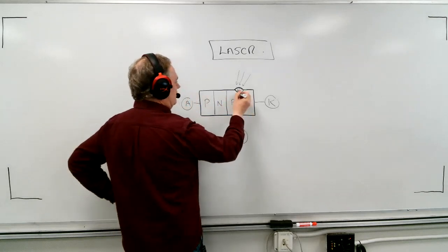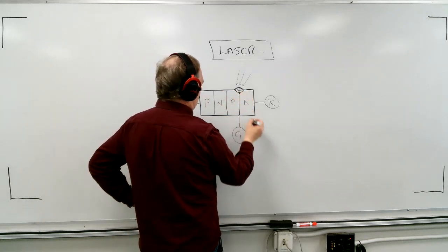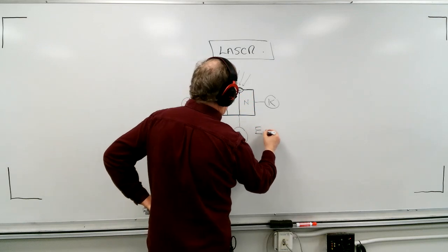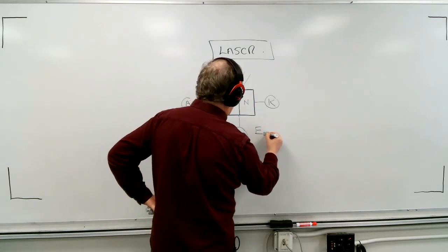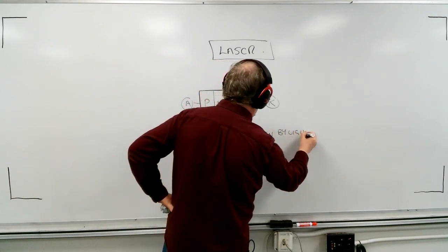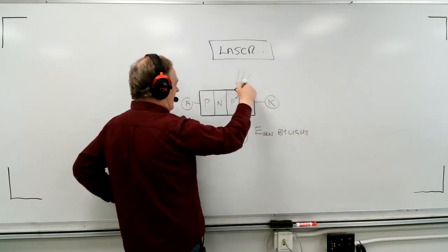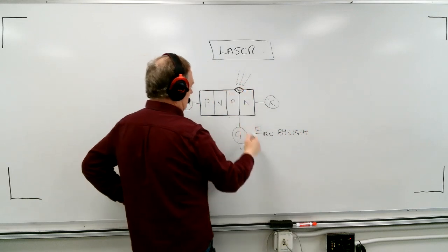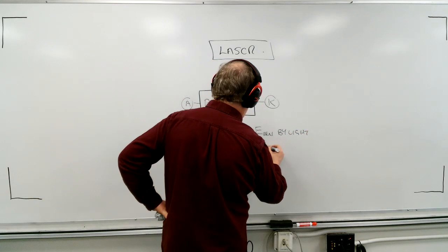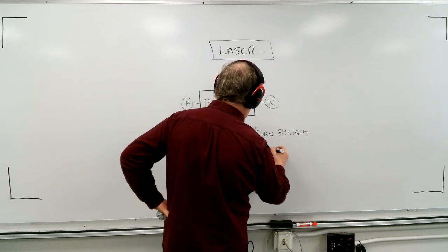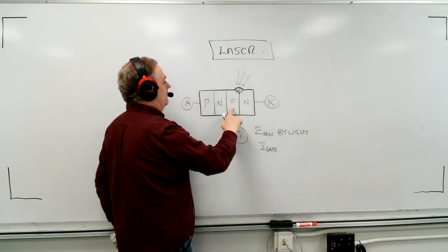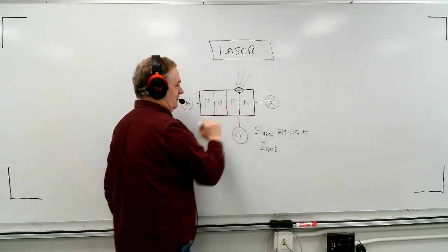And so the voltage that is created in this junction, so we're going to have E generated, okay, by the light. And it's by the light actually falling on the junction. E generated. That's going to produce I, and I'm going to call that I of the gate, because that's actually the current that will actually fire this SCR.